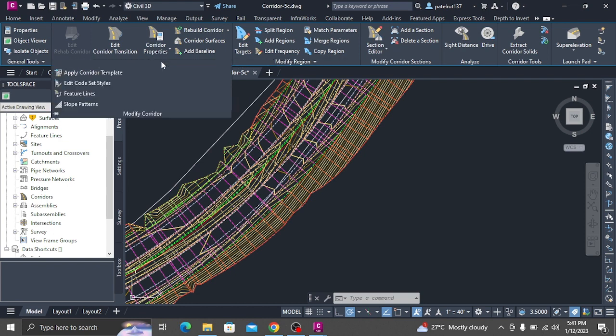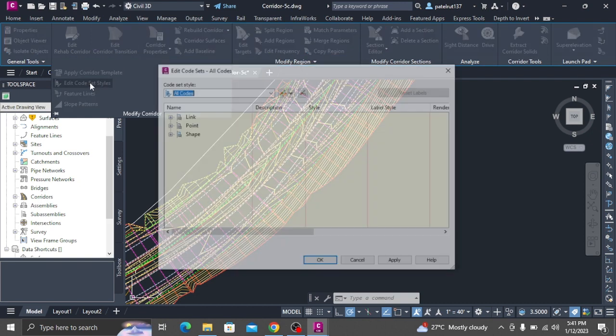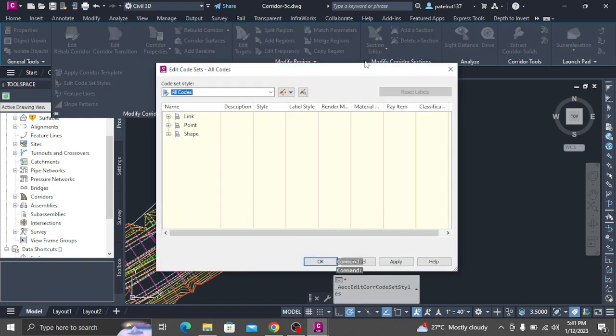On the command line, enter Render to render the corridor in 3D using the render materials that are applied to the subassembly links. Apply 2D hatching to the corridor model. Click View tab, Views panel, named Views List, Corridor_all. The drawing is redrawn to plan view. In the drawing, select the corridor.